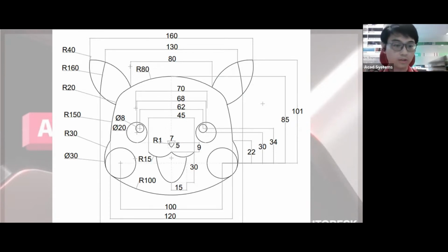Okay, moving on. We're going to focus on this bottom part. This bottom part is easy. There's no need to use arc. We can just use tangent radius because it's going to be tangent to these circles. So we select this, and the other one. What's the radius? The radius is 100. So you just input 100, click enter, and we get this. There's no need for you to find the tangent for this line as you would if you used arc. So this is the excess line I'm going to use. This line we're going to trim. Just type TR, automatically select this, then you can trim it.